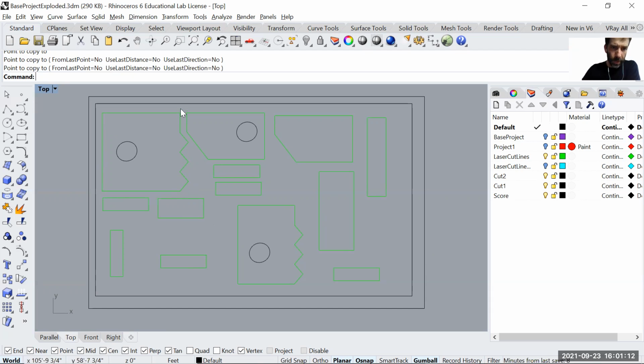Okay, when it comes to the end, this piece gets loose in the bed of the laser cutter. If it's loose, then imagine the laser comes afterwards to cut the window. That means it's not going to be precise. It's going to be cutting slightly off from what it has to be.